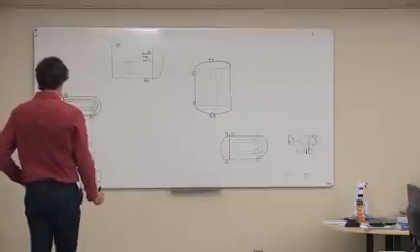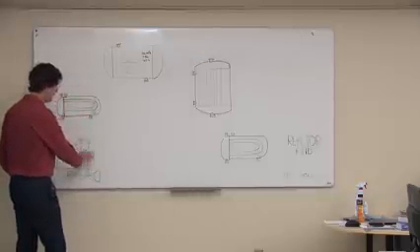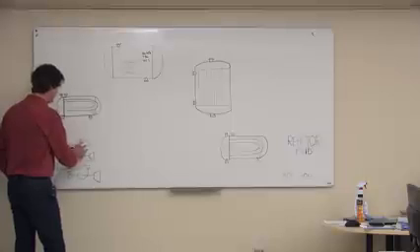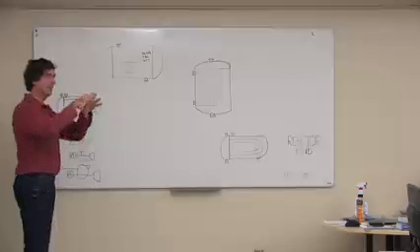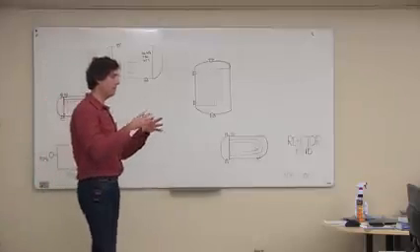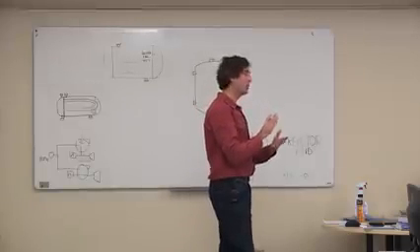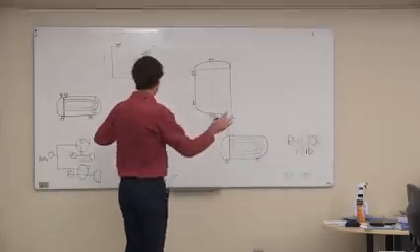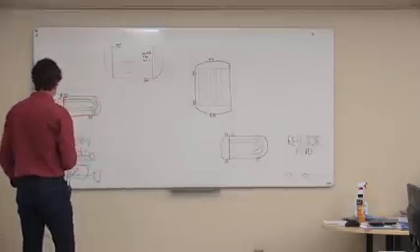Now, what you're going to find is the pumps. These are special pumps because we're going to put steam turbines on them. But in general, when you put a pump and a motor on, there's a kind of standard envelope of stuff that's just going to come. My recommendation is maybe just draw one of those on some graph paper and then photocopy it a bunch of times. And then when you're drawing your big drawings, you can just move those around until you're happy with where they're placed.